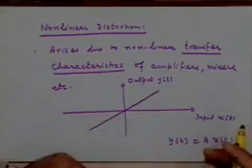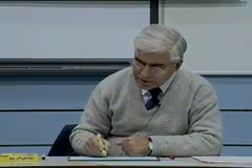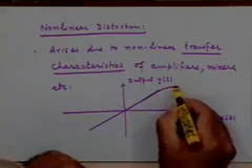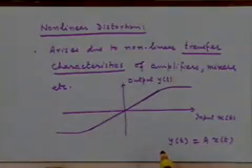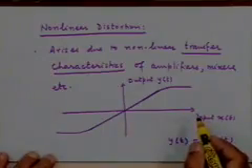Now practical power amplifiers will exhibit a kind of nonlinearity which is very commonly encountered, called the saturation nonlinearity. You know the effect. It basically arises because you have some finite values of the power supplies, and because of this, as your input signal becomes larger and larger in amplitude, instead of being linear like this, you get into this nonlinear or saturation mode like this. It doesn't remain linear for all values of the input amplitudes.